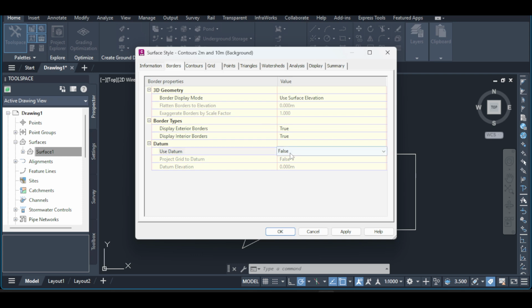Keeping the boundary on a visible layer also helps you verify it on screen. If you need a small buffer, consider drawing your boundary slightly inside or outside your target area for a cleaner edge. After you've selected the boundary, press Enter to apply. Civil 3D will rebuild the surface using your boundary choice.